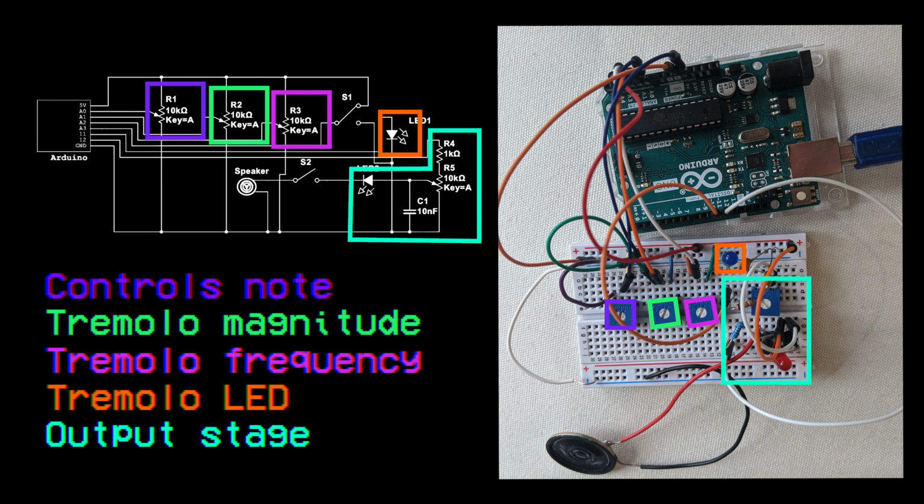Due to limitations in the Arduino functions that we used, we built an analog filter instead, which also showcases the potential for our analog synth. The potentiometer controls the cutoff frequency of the filter, which softens the sound and makes it less harsh. The output of the filter then goes through an LED and a button before the speaker, so that the notes can occur separately from the frequency and have an LED turn on whenever a note is played.